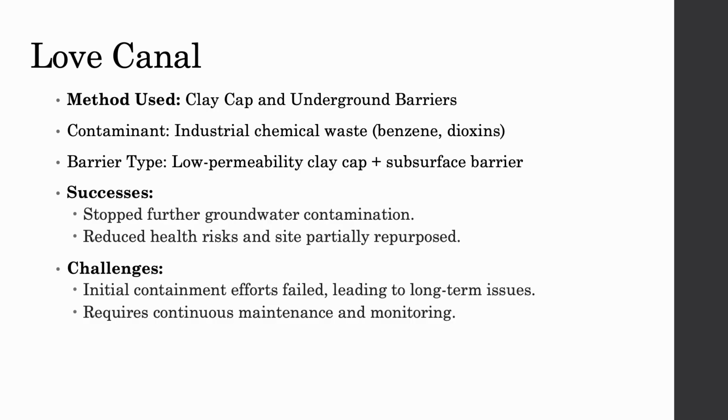Eventually, the site was capped with a thick clay layer to stop rain from soaking through and creating leachate. And underground walls were added to contain what was already in the ground. And these efforts did significantly reduce the spread of contamination and it made the site safer.